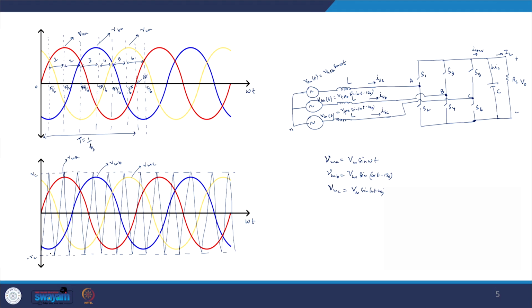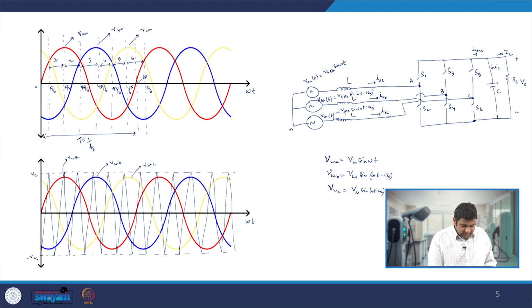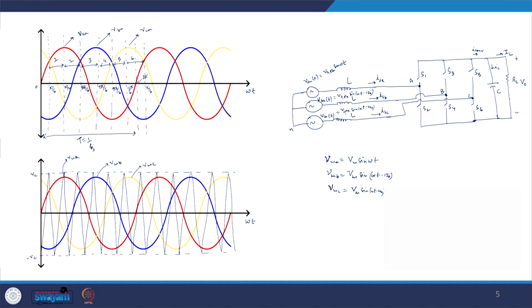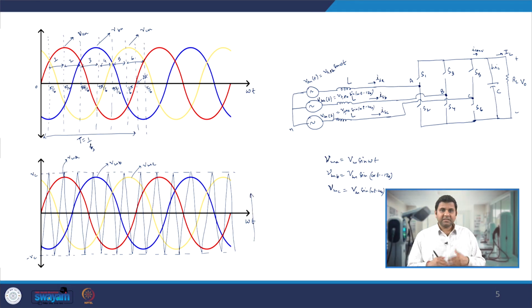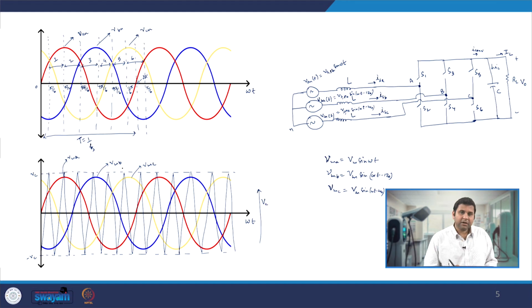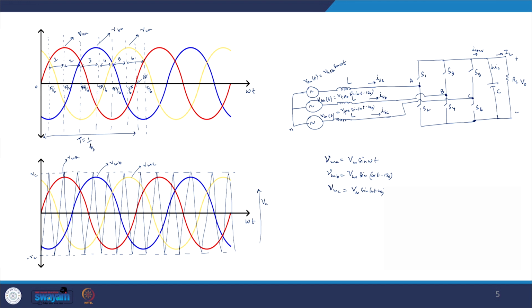So we can give a constant shift of Vc, that is when we can ensure that our carrier goes between 0 and 2 Vc, and we can just add everything together, and that is when everything gets pushed by a constant Vc voltage, and everything will come in the positive direction. Then we can take one of the instances, and in one of the instances of this mode 1 we will have this VMA, VMB and VMC voltage coming over here.